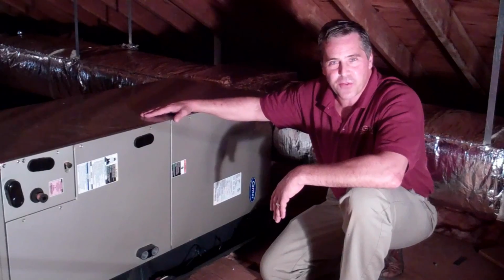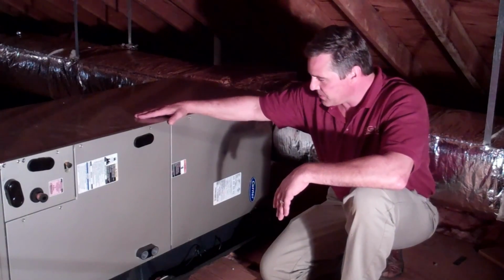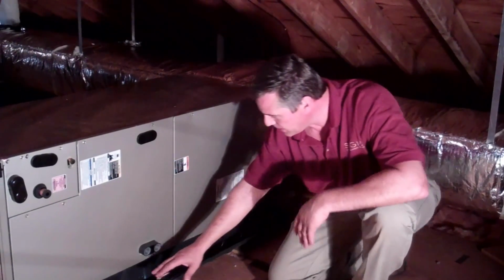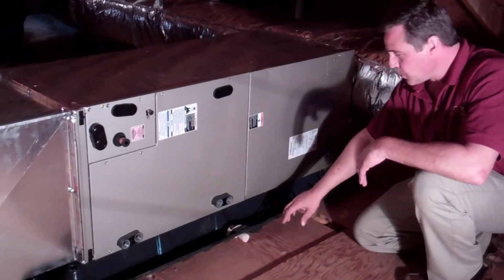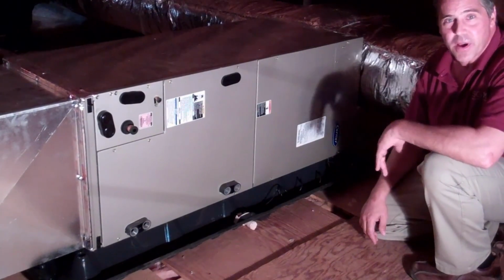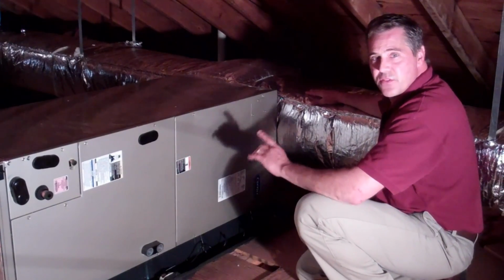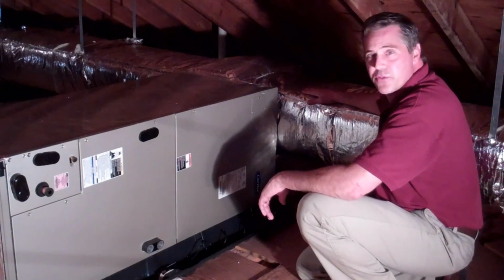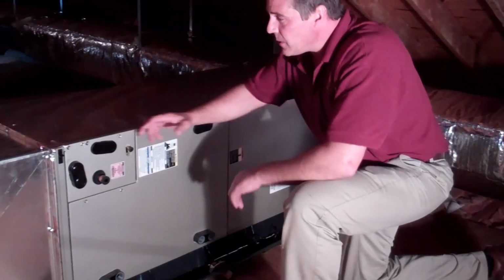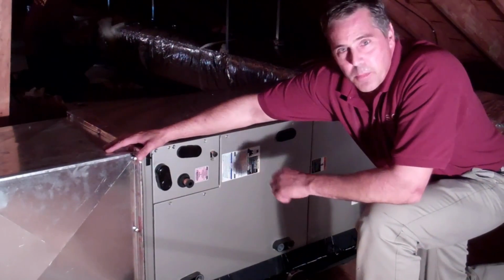I'm going to tell you how we put a central air conditioning system in a house. This is the air handler here. We put an emergency drain can down so we don't get any floods. We put a float switch in there as well to protect you. This is the supply duct right here, which is fully insulated and sealed, and this is going to distribute the air throughout your house. This right here is the return side. This is going to pull the hot air out.